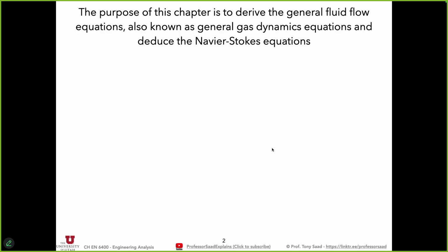And that was satisfactory for something like mass, or even energy, right? But when we got to momentum, something was off. I personally wasn't satisfied when I told you the diffusive flux for momentum is mu grad u. And you're like, okay, but what about Newton's second law? How does the balance equation that we derived connect to Newton's second law, which is conservation of momentum? And so something was off.